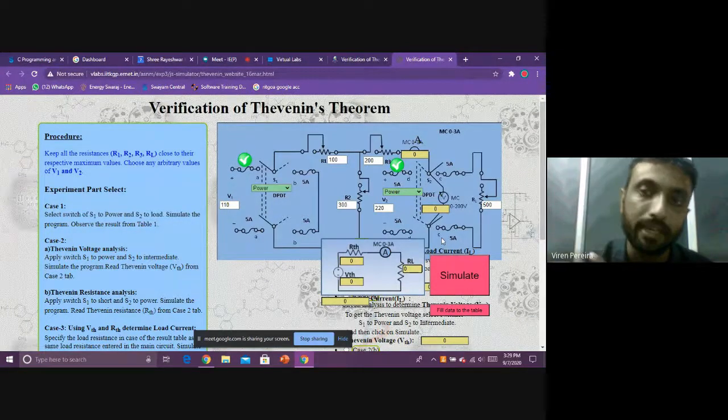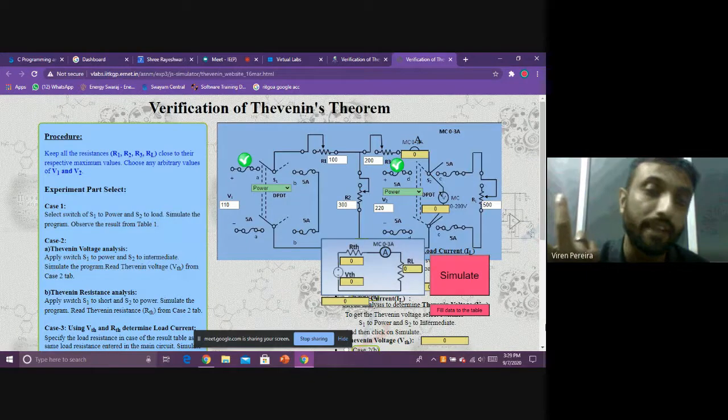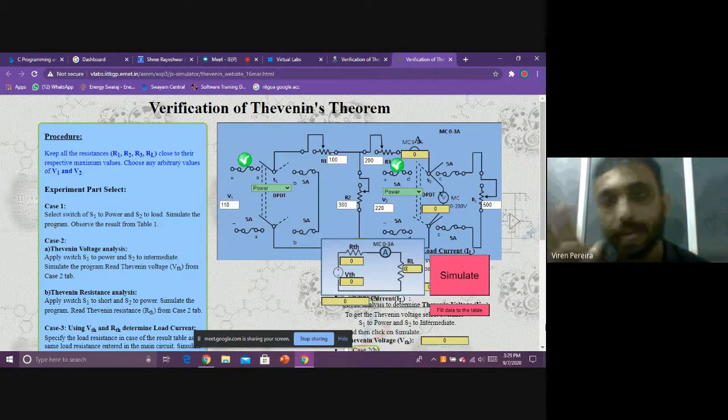Connecting wires you can get from your LAN wire only. If you have broadband at home, just cut the extra wire and take out. Those are your connecting wires, what you'll see in RIT. Resistors will cost you some 25 paisa per resistor. And voltage supply, you all will say, from where will we get 5 volts, or 12 volt supply? From your adapters. Even your mobile chargers have 5 volt supply, so you can use it from your mobile chargers as well. You can connect the wire and derive the 5 volt, and you can see how it works. That is practically doing it.